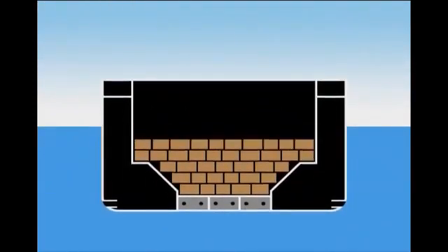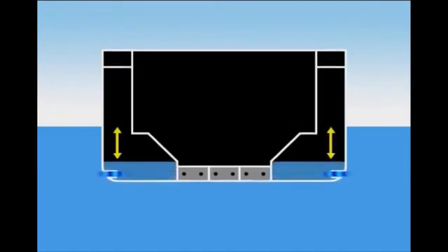As cargo is unloaded and the water level inside the ballast tank becomes lower than the sea surface, ballast water is gravity filled into the tank thanks to water pressure head of the seawater. Ballast filling stops when the water pressure head becomes zero, as the ballast water level rises to become equal to that of the sea surface.